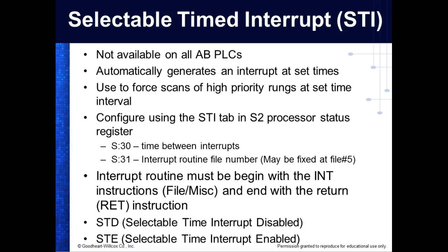So if you ever looked at the pin out of a microprocessor, you're going to have two pins. One of them's going to be called IRQ, and one of them's going to be called NMI. NMI is non-maskable. And they don't use that thing all the time, because that means the processor will not ignore that value. The IRQ, though, which is the maskable interrupt, that means I can do what?